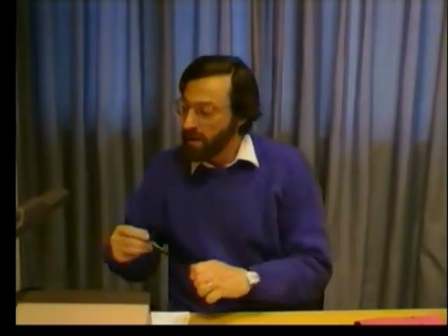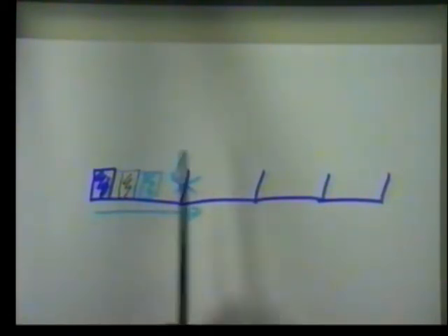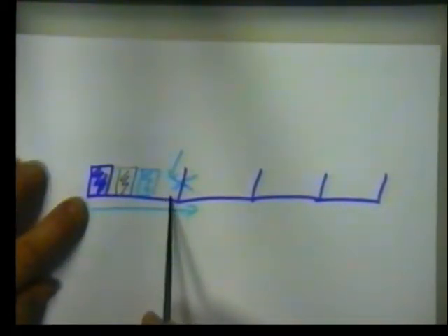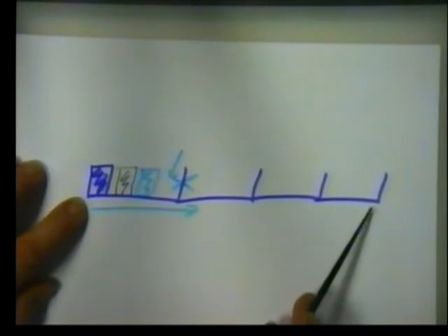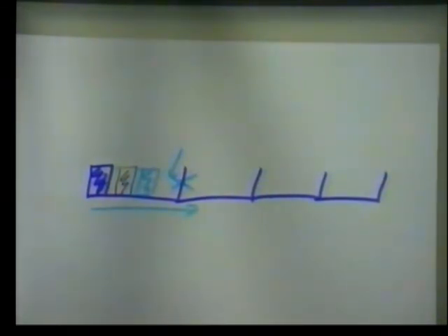And if they all coincide, they've all got to be executed and got out of the way before the next fastest one arrives. So therefore we get this rule, that I've drawn diagrammatically there, the sum of the execution time of all your interrupts must be faster than the rate of arrival of the fastest interrupt. It's essential. It's absolutely essential, or it will not work. So let's do some sums on this, and we'll look at a real situation.